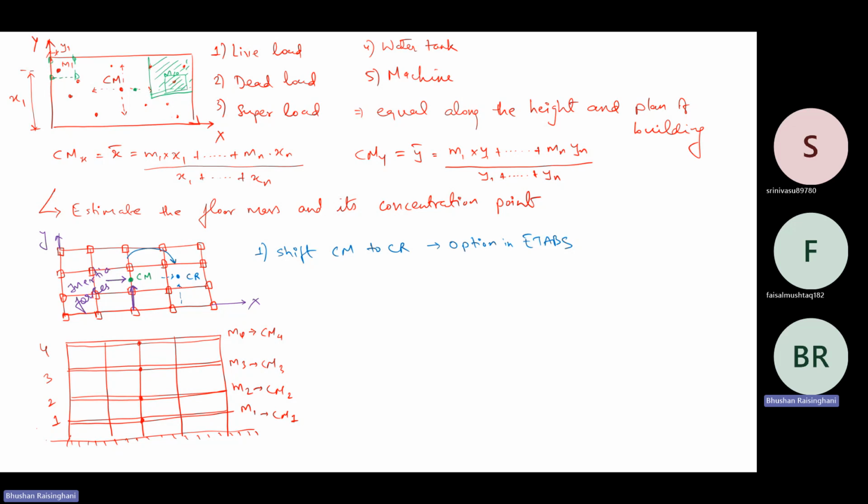There is no necessity to estimate the eccentricity, right? This you can do in the software also. Second, you estimate eccentricity. That is a static eccentricity that we call ESI. Okay, that is the difference between CM minus CR. It is never CR minus CM. It is CM minus CR. Is it correct? What is the formula for this? CM minus CR or CR minus CM?